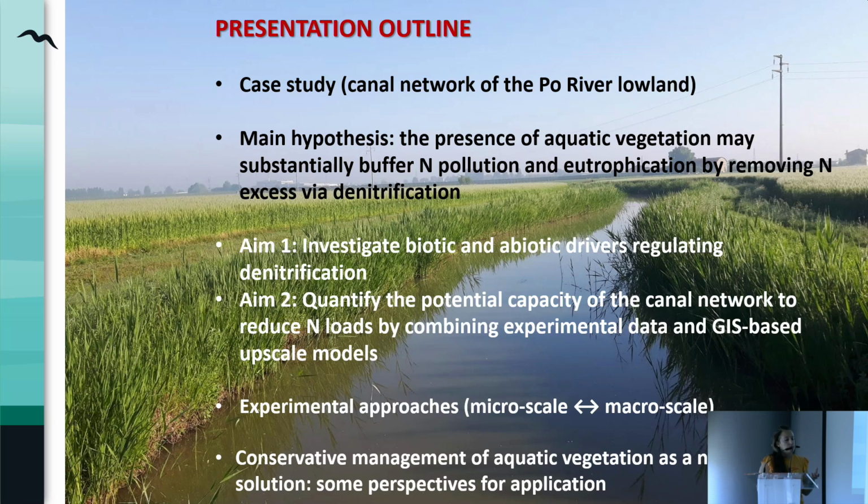These are microbial processes. Our aim was twofold. First, we tried to investigate the biotic and abiotic drivers that regulate this microbial process. And the second aim was to quantify at the watershed scale the potential capacity of the canal network to reduce nitrate loads. And we combined experimental data and GIS-based upscaling models.